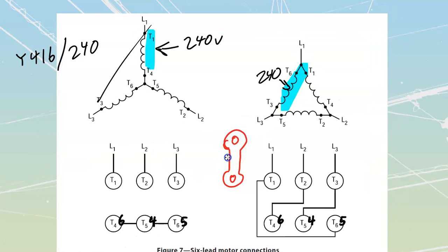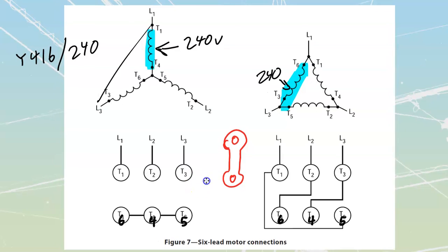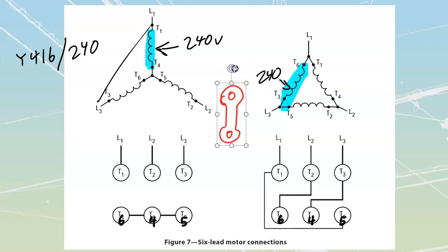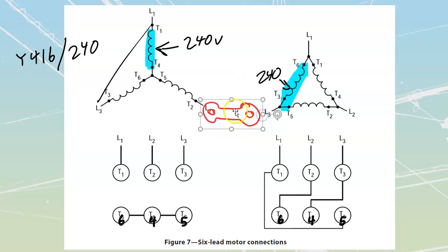These are going to be studs that are in the background on these actual motor terminals. So these are going to be little brass pillars that come up. They're going to be threaded. They're going to have nuts on them so that we can grab them. And then these connections over here are going to be able to be made directly across from component to component like that. Or if I want, I could turn these things sideways and use them like that.